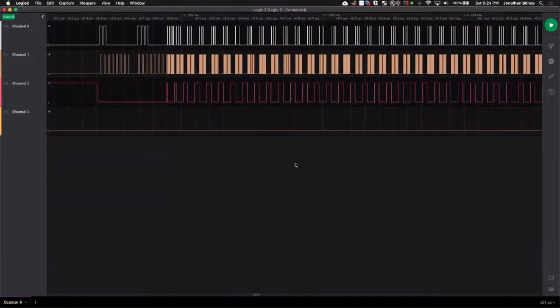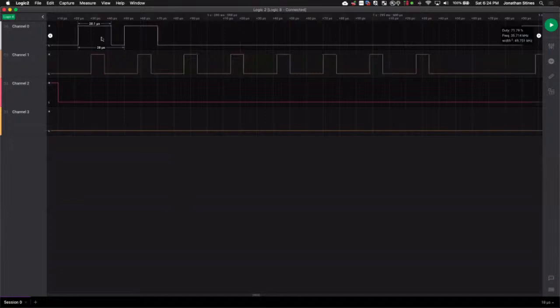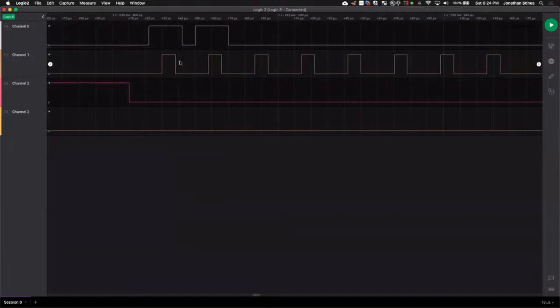There's a lot of opcodes being set. There's a lot of different various settings being aligned with the actual device. And typically that's one of the first things that'll start communicating, as we can see here. So we zoom in, and a little bit of a telltale thing is that we're starting to see some type of communication taking place right here, a little sporadic.